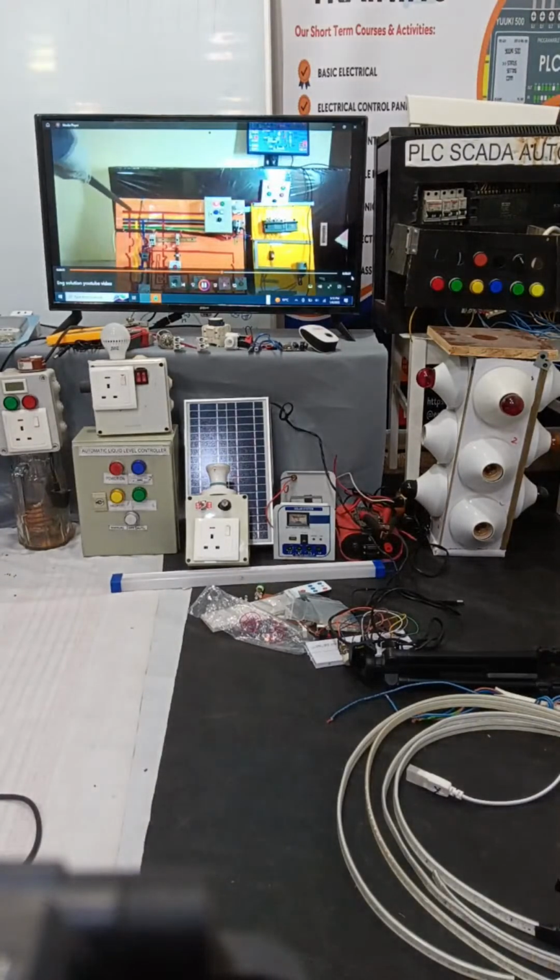This is the circuit diagram and the light circuit of a motor control system. In place of a motor, here we have a bulb. These are the push buttons, the start push button. We can start the motor, and we can stop with this red push button. And these are the indication lights. This green light glows when the motor runs. The red lamp glows when the motor is off. And if for some reason the motor draws heavy current, the motor will trip and the yellow lamp will glow.